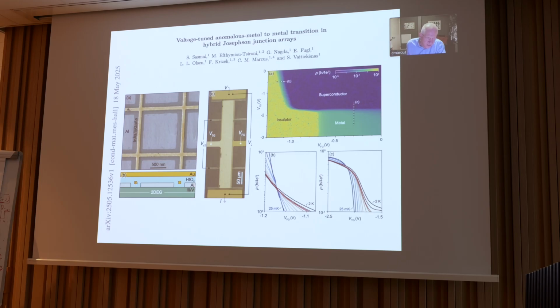Finally, there's a gate just drawn by that yellow square, which is the gate that's shown, and then an insulating layer, then a second gate over the top. Now, I know it's getting complicated, but this complication is worth it, so bear with me for a second. This looks a lot like the two-dimensional grid of superconductors. But now, instead of depleting the grid in one way by depleting the semiconductor, you can deplete it in two different ways. The first way you can deplete it using this lower gate, which we call a frame gate, allows you to, as before, shut off the connections between all these superconducting islands by depletion.